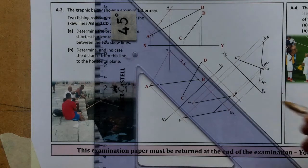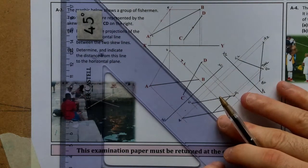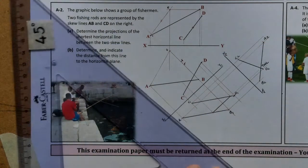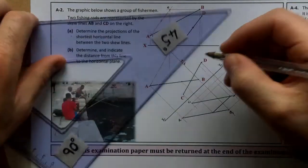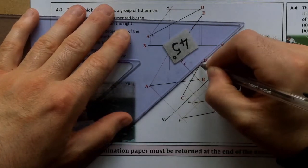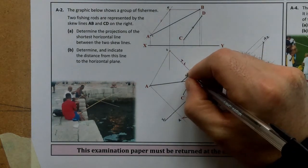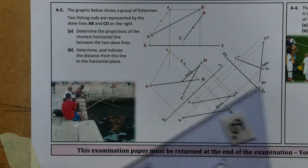that point right there, it's important now obviously being very accurate using sharp pencils. So half a mil makes a big difference here. So to find those points here, I've got the line here on AB and I've got it on CD here, so that's how it would appear in my plan. And this is the making or breaking of it here. So this is the shortest horizontal line, as it appears in my plan, and now I have to find it in my elevation.